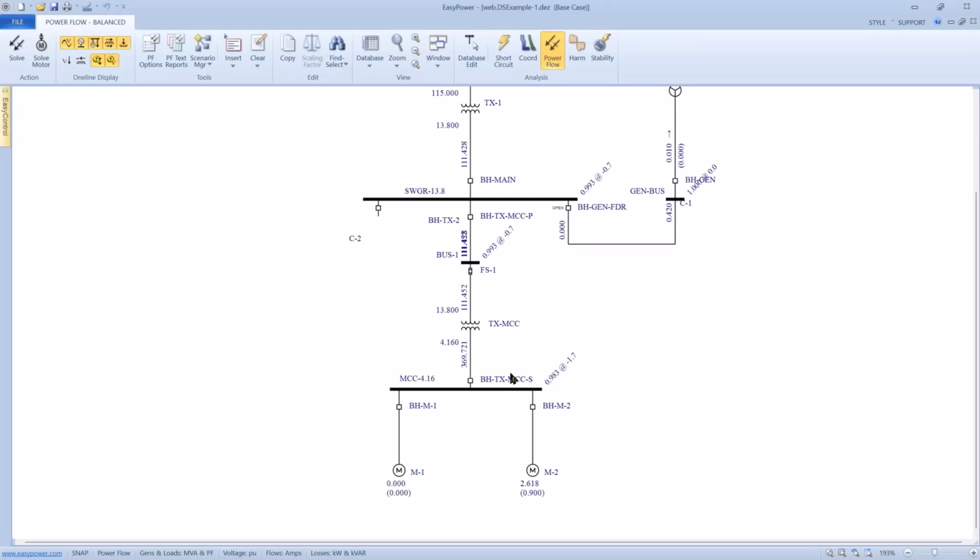We're at quiescence and power flow. We're drawing 360 amps. If I do an impact motor start with this little icon up here on the top row on the left side, it again calculates the instant I apply the load across the line with that very low power factor. And you can see the current is 10 times what normal current was for a single load.